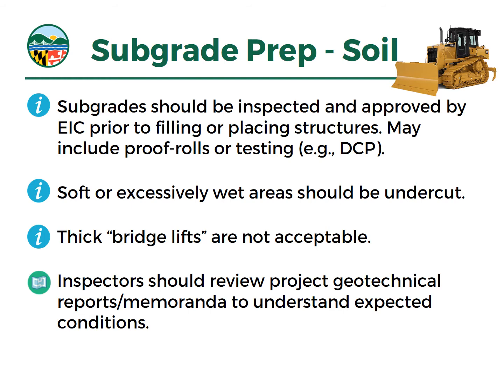We would strongly advise against thick bridge lifts. They work in the sense that they can result in stable working platforms, but now you've got this thick mass of poorly controlled soil, probably in a critical location. It may be a preferential pathway for seepage or promote differential settlement and cracking at a later date. So we avoid bridge lifts where possible.